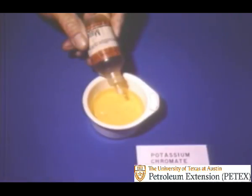Another test made on the filtrate is the chloride test, which measures how salty the mud is. Adding a few drops of potassium chromate turns the filtrate sample yellow if salt or chloride is present. This test is useful to determine if salt formations are being drilled or if saltwater flow has been encountered.